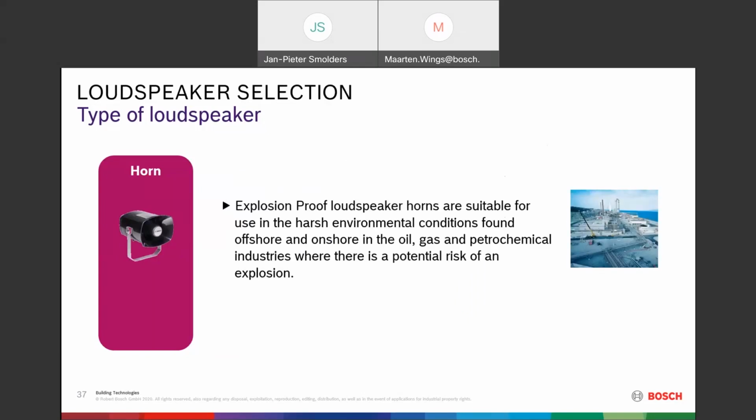And another specific one is the explosion-proof loudspeaker. Now this loudspeaker is sealed, so gas or dust cannot enter the horn. So if inside the horn there would be an electrical spark or something like that, it will not cause an explosion. So for factories with oil, gas, this horn on the outside could be a good choice.